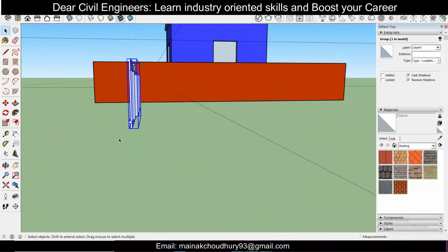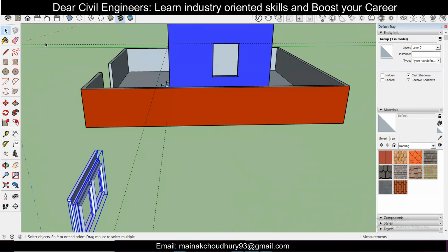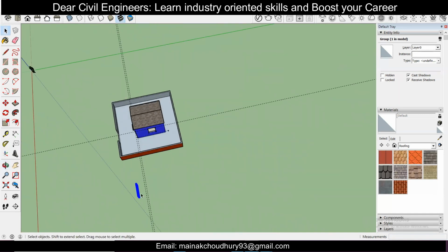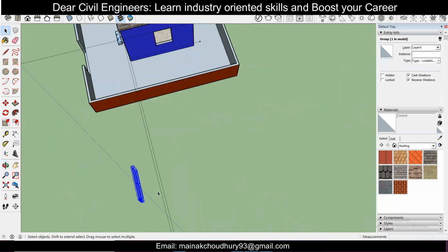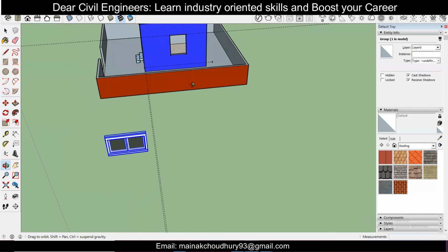For rotating it, we'll go to the top view like this with the arrow for the mouse, and after that we'll use the rotate option, and make sure it is along the blue axis, and we'll draw an axis here and then rotate it 90, and after that we are done.